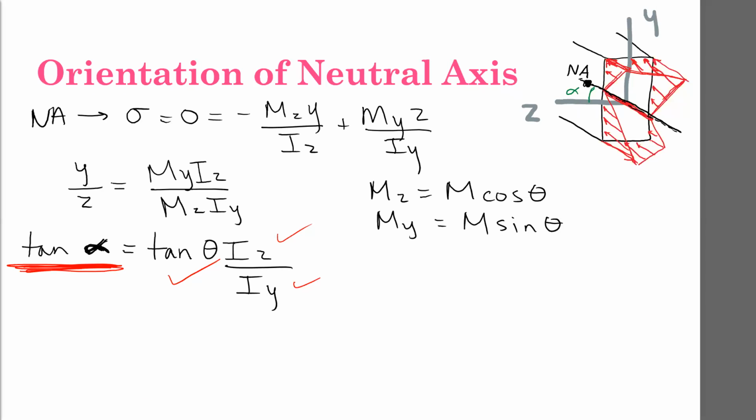What you're referring to is having a horizontal neutral surface and then a moment about a horizontal axis. Yeah. That's when the moment is about a principal axis. But today we're talking about when the moment is about an arbitrary axis, not one of the lines of symmetry of our shape. Okay, cool.